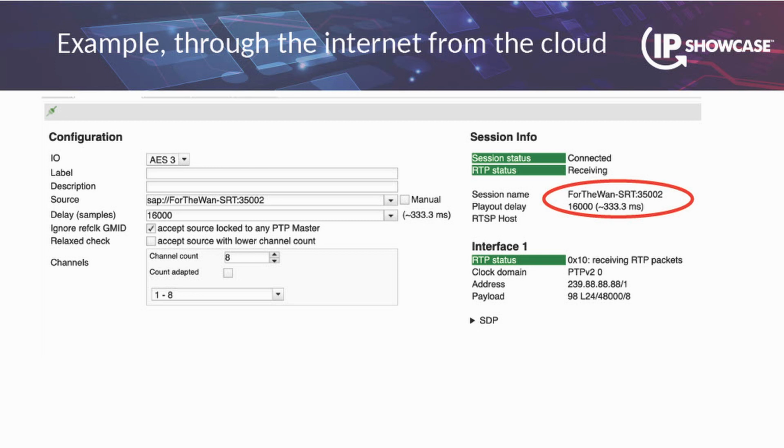And we exchanged streams between Ross Video that was in Ottawa and our business center in Lausanne, and then with DirectOut also in Germany. And here we can see that we needed to configure 300 milliseconds of receiver delay to be able to receive this stream. And the receiver delay comes from the network, the geography, and also the SRT protocol that we will see just after.